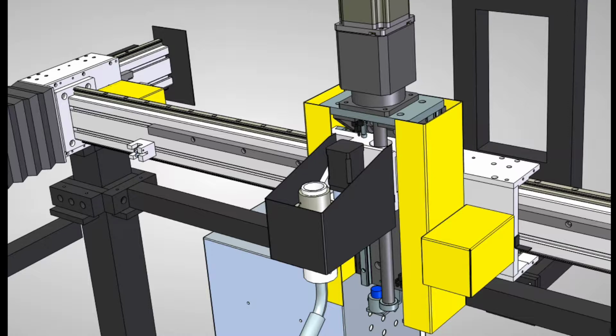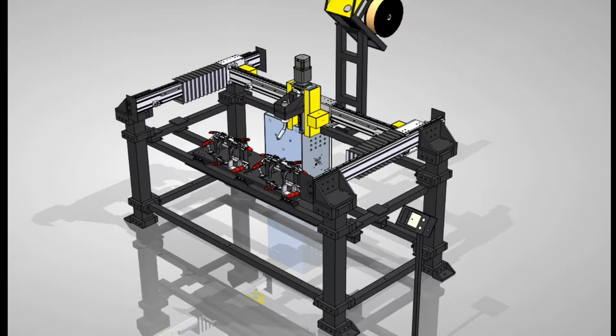But before that, let us talk about the axes. We've got an X axis, we've got the Z axis. We have zoomed in on the Z axis with the rotary axis. Z axis has a stroke of about 300, and the rotary is again plus minus 360 degrees. Then there is the Y axis on which the entire Z axis is mounted. Y axis here is about 1.2 meters in stroke. And for the X axis, we have a dual X here. As you can see, the dual X covers about 1.5 meters in stroke.